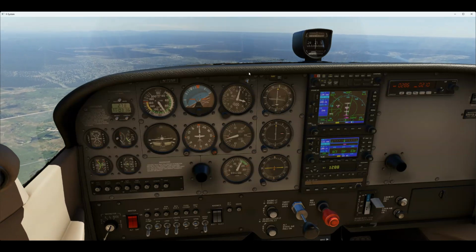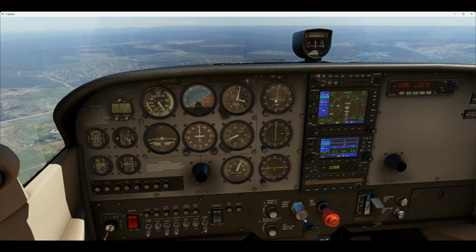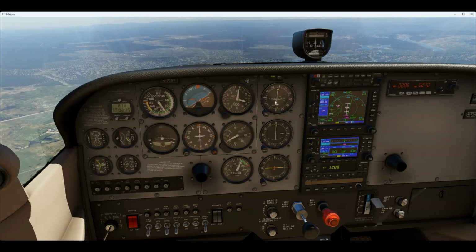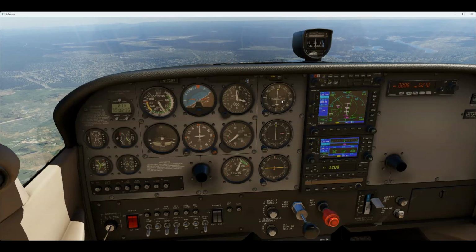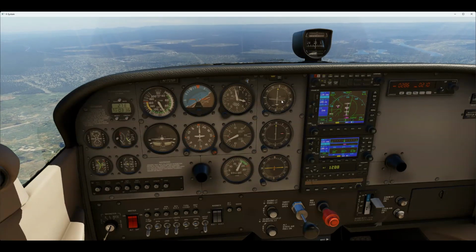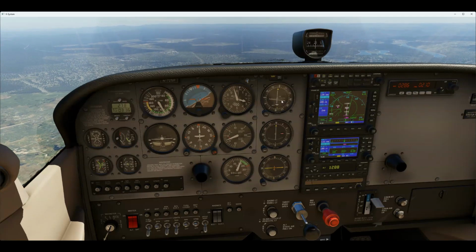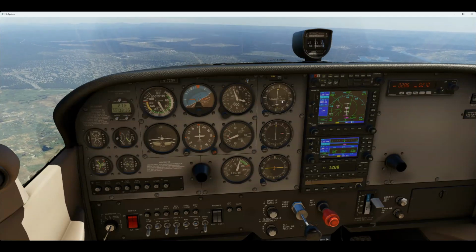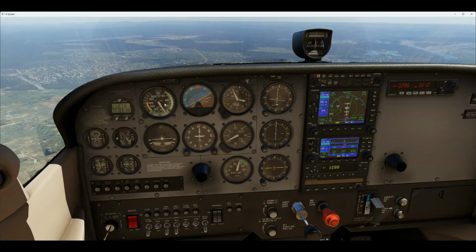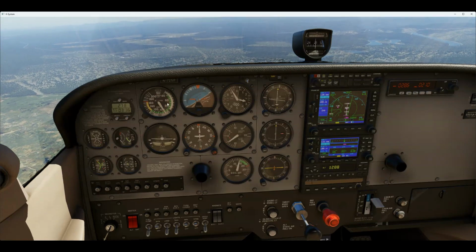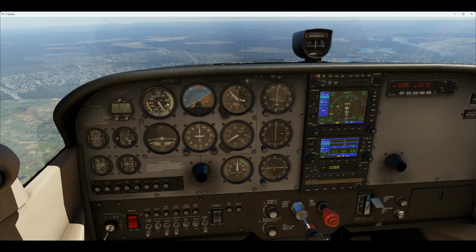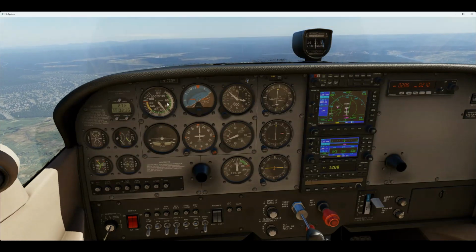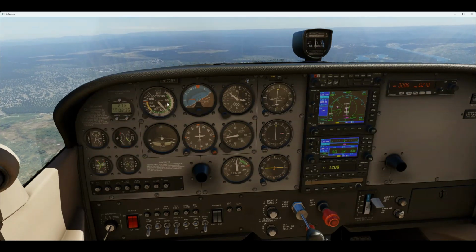You can see I'm good on the localizer. I'm not good on the glide slope, it's telling me to keep flying down. So I probably want a little bit more than that initial glide slope heading. I want to get into the white arc on the airspeed indicator, so I'll reduce the power a bit more and reduce the speed a bit. I keep the descent coming, but that allows me to get the nose up, which allows me to get a stage of flap in.